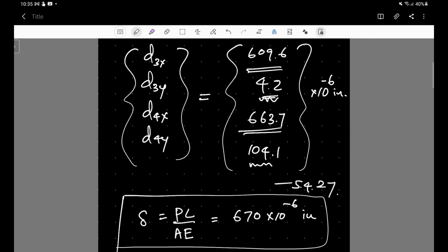So as a conclusion, we can say that the result seems to be reasonably correct. Our finite element simulation model seems to be all right, and the deviations can be attributed to the coarseness of the mesh. And the displacements in the y direction are due to the effect of the Poisson's ratio.